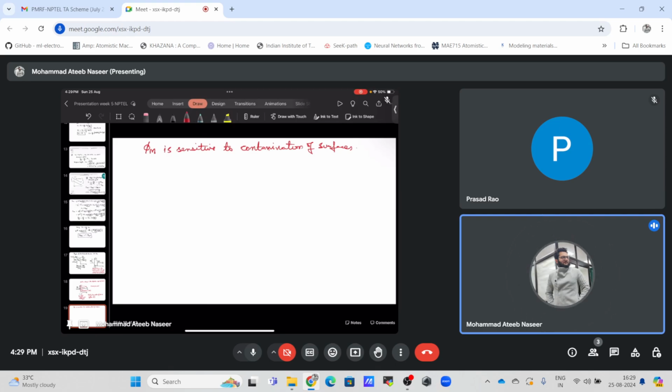I guess that's quite an advanced thing to show, because the professor must have already told you that. So let me draw the p-type semiconductor. For a p-type semiconductor, the Schottky barrier will simply look opposite to what we have drawn. If this is the EC, this will flatten out. This is the EF, this will be the EV, and this will be my barrier q phi B dash.